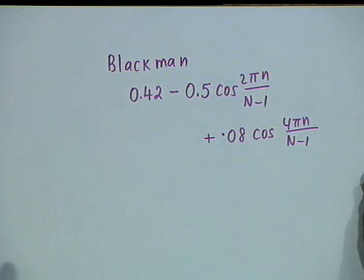It shows its teeth in amplifier rise time and bandwidth. The smaller the rise time, the larger is the bandwidth that you require. And bandwidth is a very costly phenomenon. So this is also an uncertainty relationship.